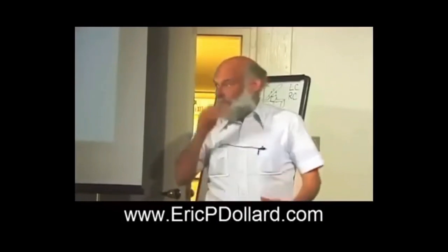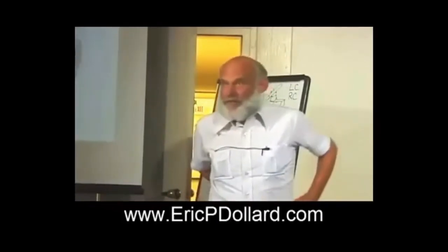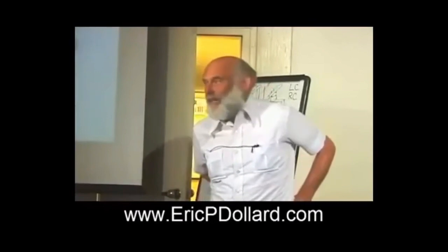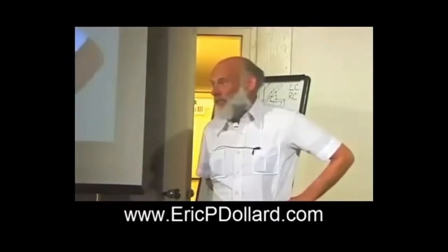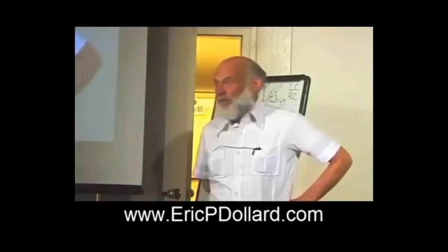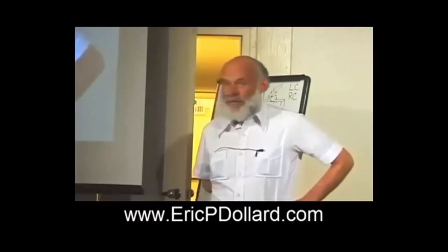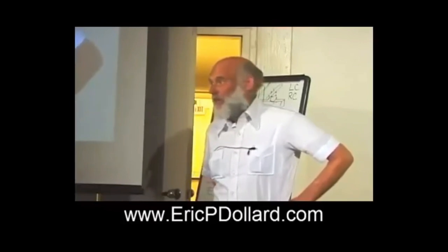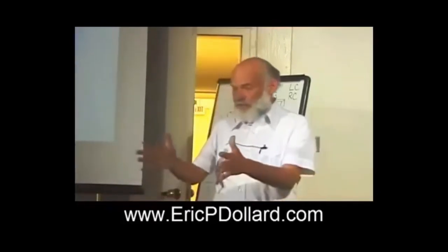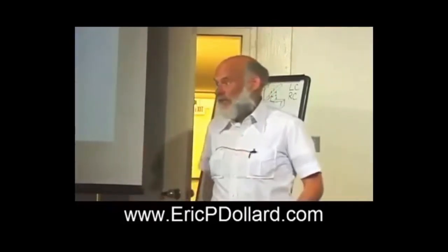What was the frequency of this transmitter? This one operated, the frequency's immaterial pretty much, but it's got to be an HF band. It operated at 3.3 megacycles. The voltage was about 60,000 volts. The electrode area at each end was about maybe 15, 20 picofarads of capacitance. So basically the tube sat between the plates of a capacitor, so to speak.